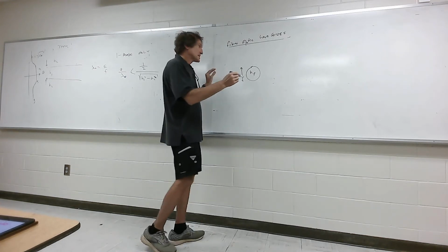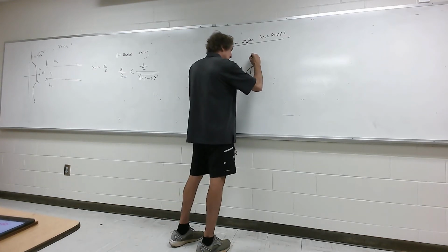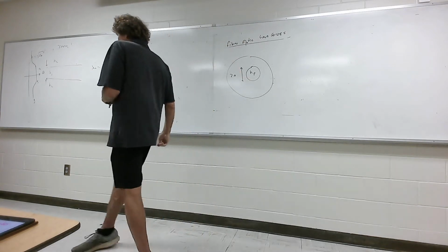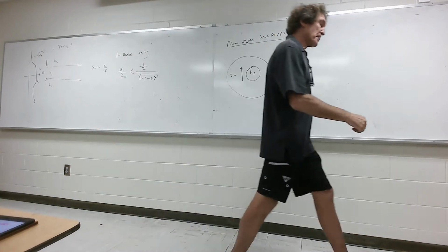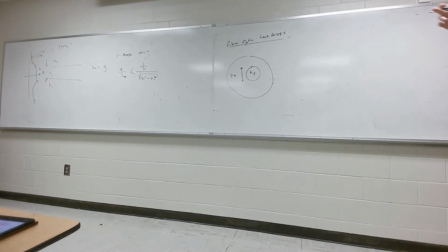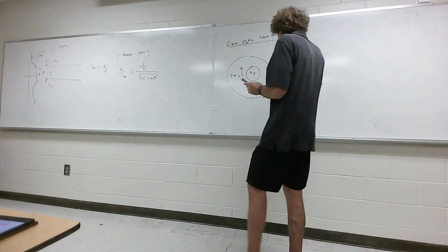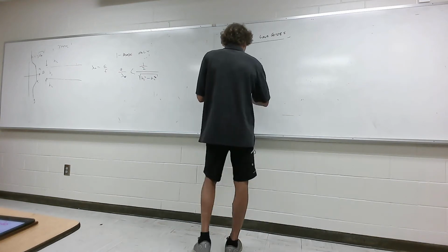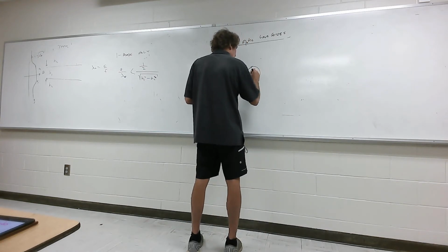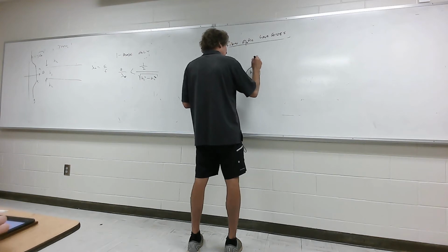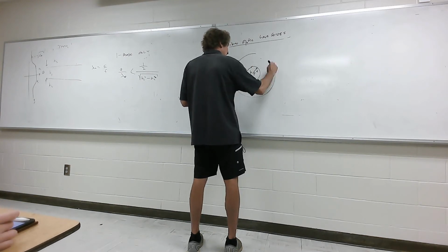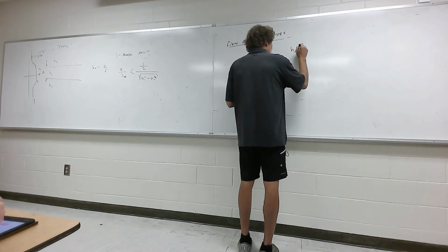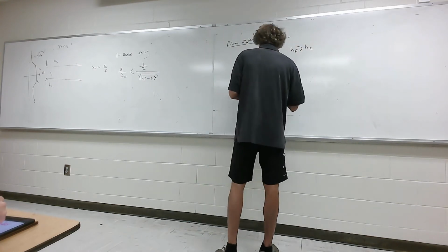And it's surrounded by something called a cladding. Around there, that's not drawn right, but around there there's going to be cladding. And that cladding is just like the sandwich over there in terms of the values of N1 and N2. Let me just draw this up here. So you're going to have this, with a radius of A, and then you'll have the cladding, NC here. Now, NF will always be greater than NC, or this thing won't work.